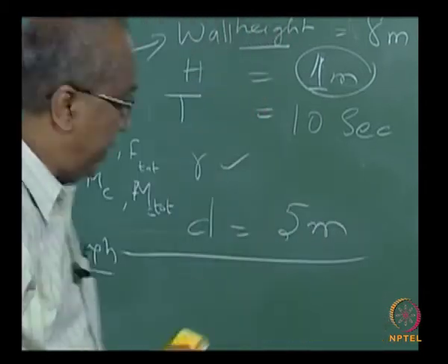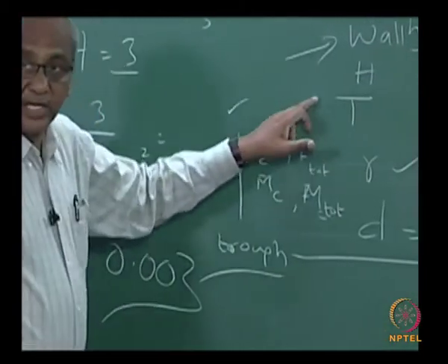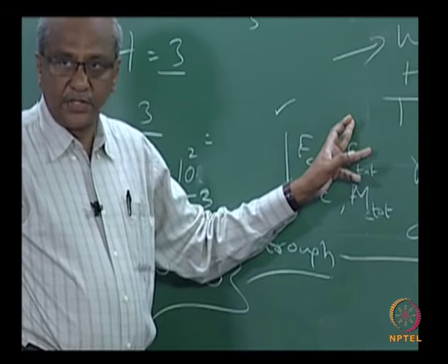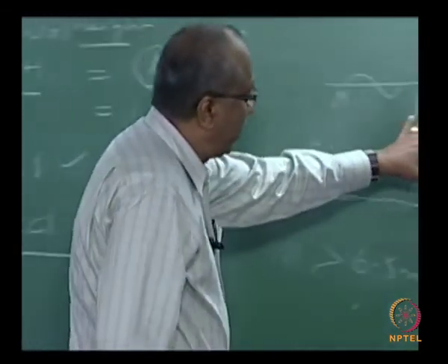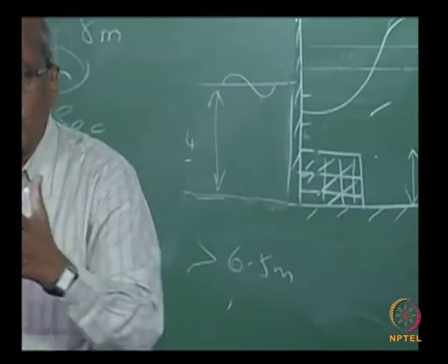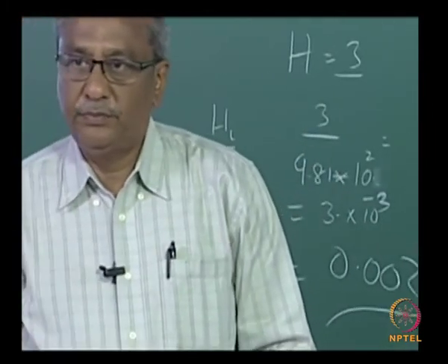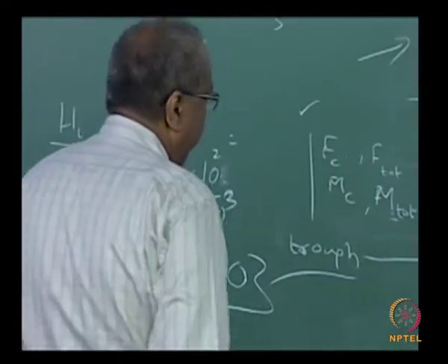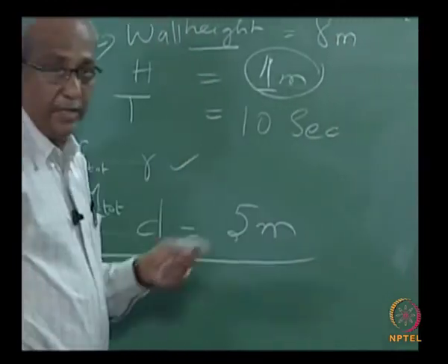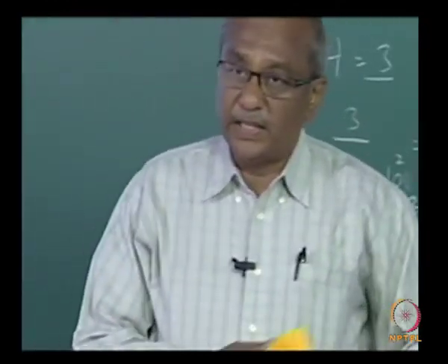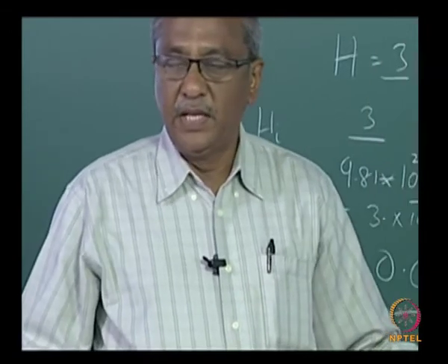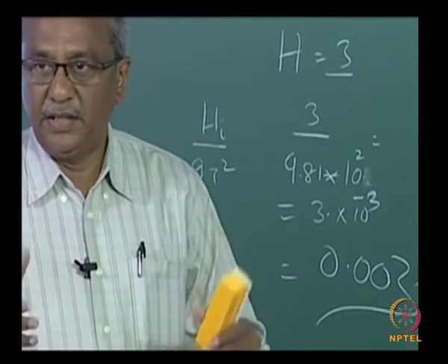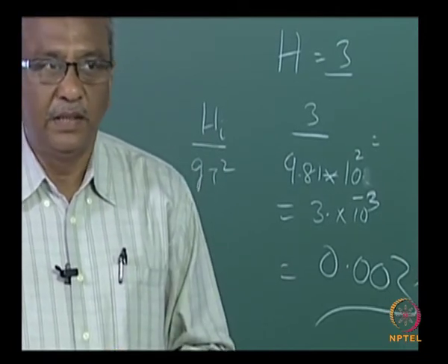That reduction is also going to be dependent on the wave characteristics. All these wave characteristics come into the picture, you understood. So all these combinations need to be worked out when you are really dealing with a problem. Have you understood now how to deal with such a problem? And also you need to complete all this exercise with a range of wave heights, range of periods, and make sure that the stability is assured for the complete range of wave characteristics you are working in the field.